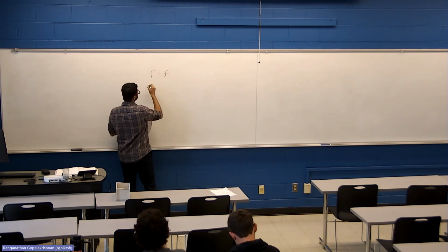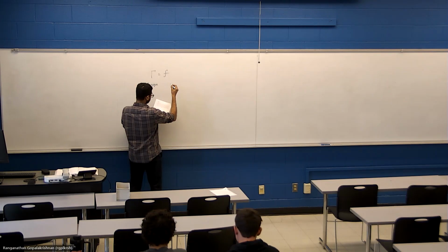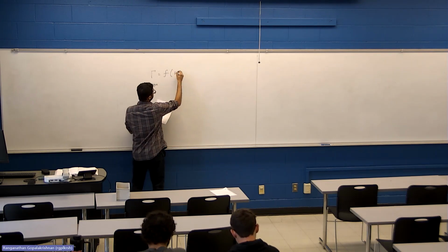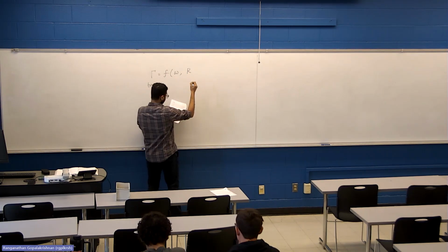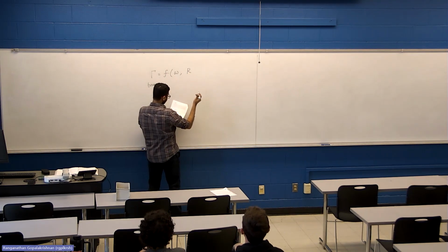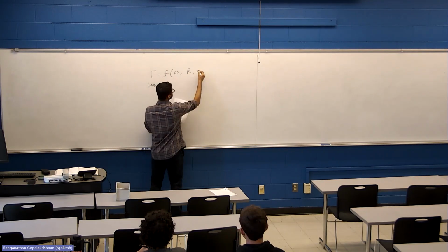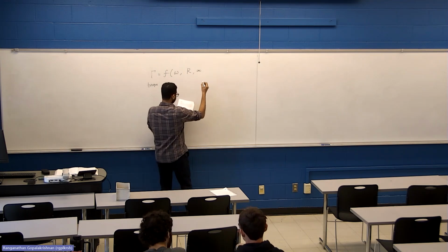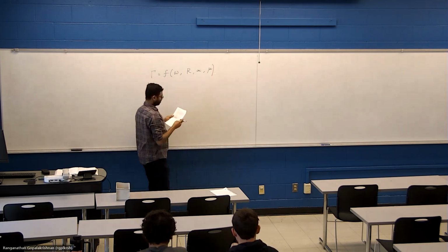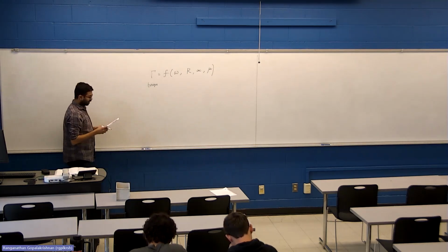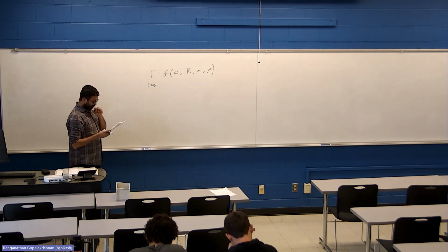So the torque is a function of omega, the rotation velocity or angular velocity, radius of the cone, and the angle alpha, and this fluid viscosity mu. With the aid of dimensional analysis, determine how the torque will change if both viscosity and angular velocity are doubled.